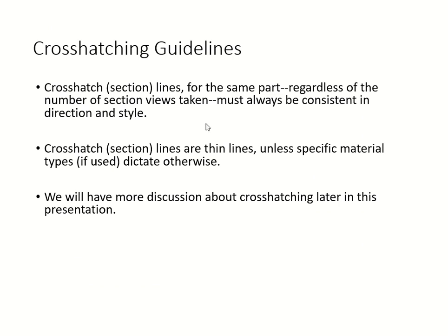Cross-hatching guidelines. Alright, so you crosshatch your section lines for the same part, regardless of the number of section views you do, okay? You've got to always make sure that they're consistent in direction and style, yeah? And I will show you, of course, when you're reading this, it's pretty difficult to get it. But when you draw, everything is super easy, yeah?